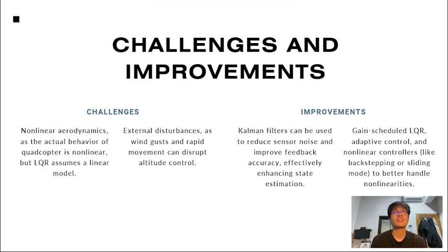For the improvements, first, Kalman filters can be used to reduce sensor noise and improve feedback accuracy, effectively enhancing state estimation. Next, gain scheduled LQR, adaptive control, and nonlinear controllers like backstepping or sliding mode to better handle nonlinearities.